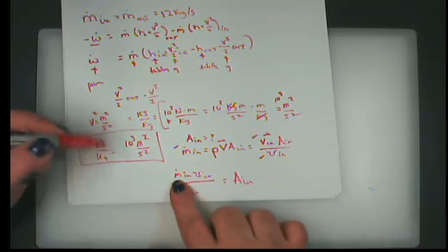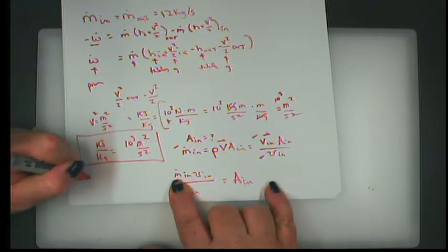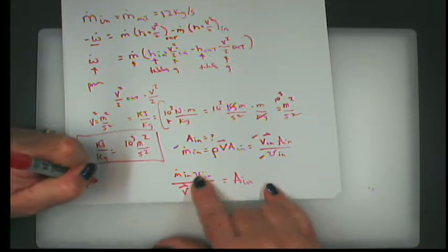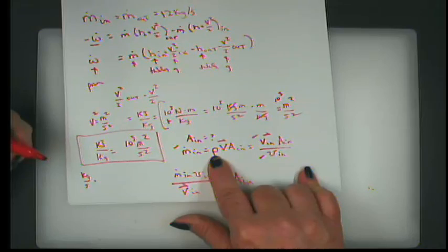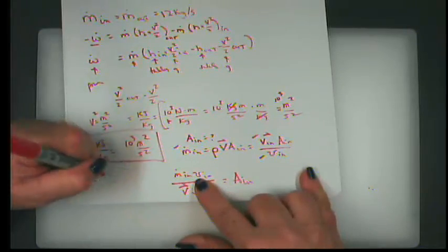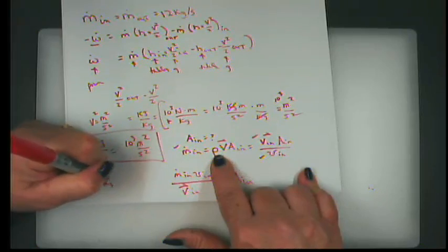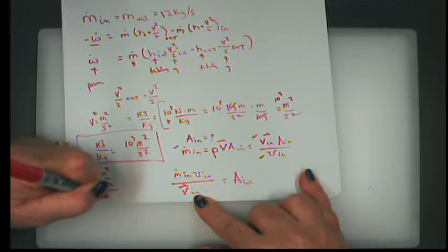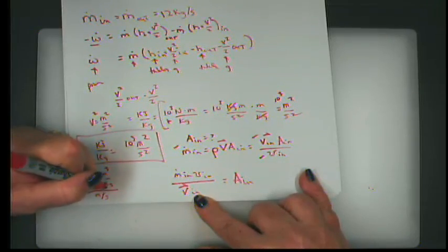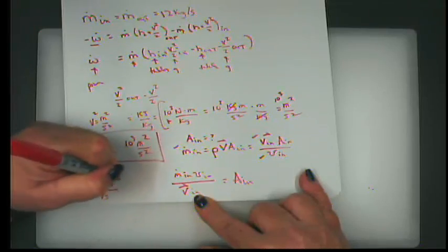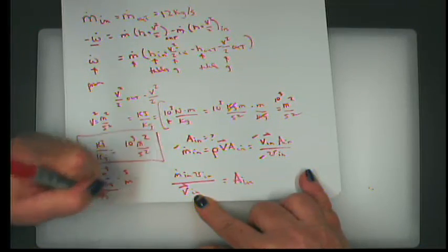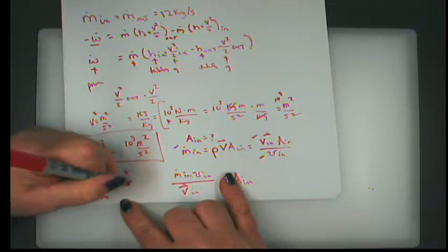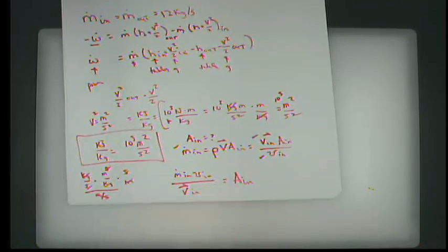Now, let's think about units, make sure everything comes out all right. M dot is in kilograms per second. Little v is the reciprocal of rho, so this is in meters cubed per kilogram. Divide that by meters per second. So we have kilograms, kilograms. We have meters down here, seconds up here when I flip it. So that'll give us meters squared. So we have dimensional homogeneity with that equation as well, because meters squared is a good unit for area.